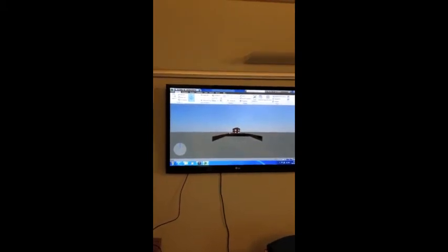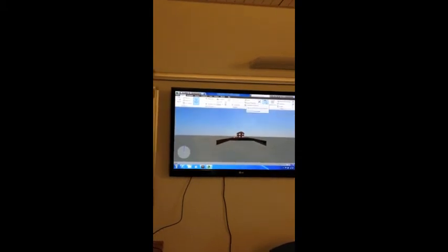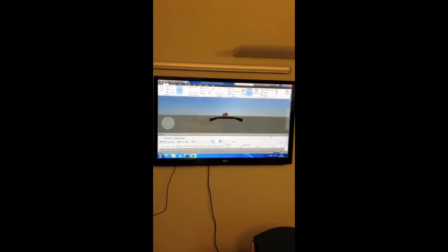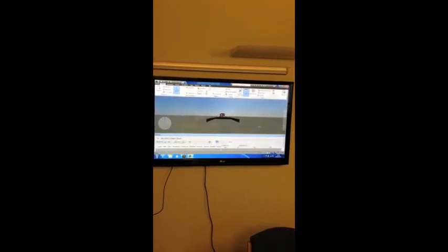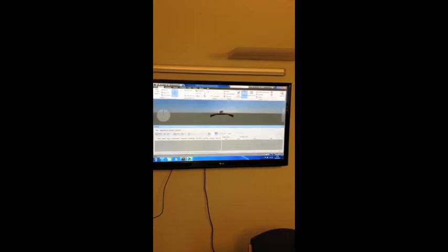Once the model has been opened up, you need to go onto the Tools tab and click the Timeliner function. And this will open up in a box at the bottom of the page, which you can make a little bit bigger to make it easier to read. You then need to import your ASTA programme into the Timeliner.